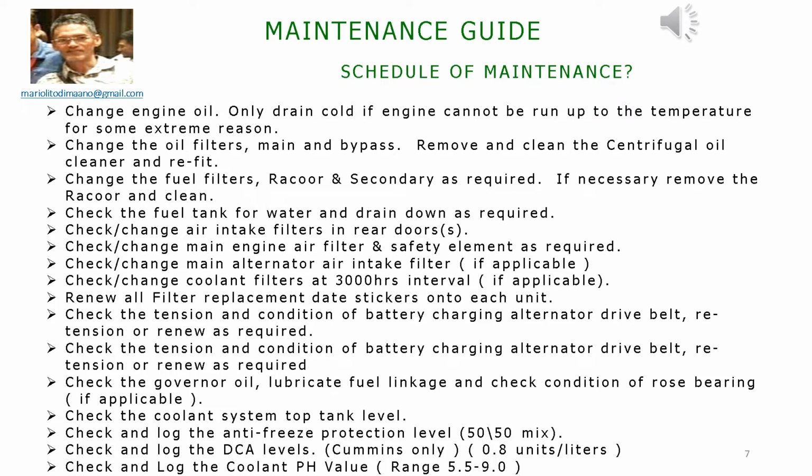5. Check/change air intake filters and rear doors. 6. Check/change main engine air filter and safety element as required. 7. Check/change main alternator air intake filter if applicable. 8. Check/change coolant filters at 3000 hours interval if applicable. 8. Renew all filter replacement date stickers onto each unit.